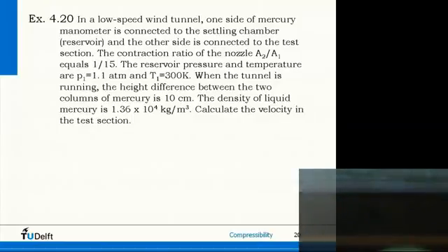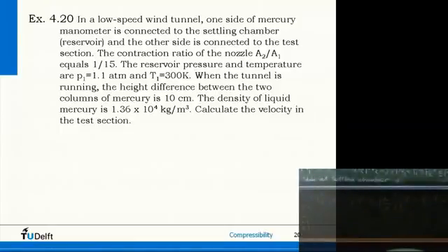Yeah? And this is how velocities are actually measured. So if you know pressure differences from manometers or pitot tubes, as I will explain in a minute, if you know contraction ratios, so areas, and somewhere a density for incompressible flow, you're there. You can apply this relation from Bernoulli and find it.